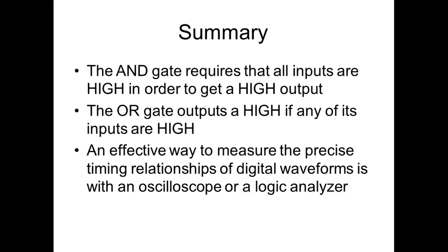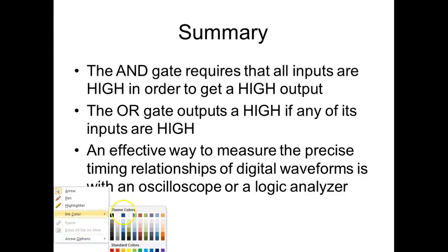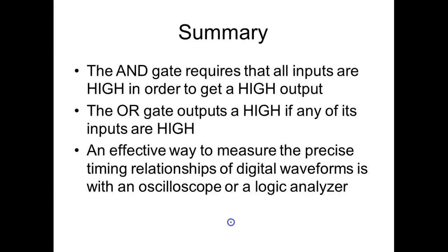for a lot of people, they'll look at an AND gate and they'll say one input is pulsing and they'll see the other input is pulsing. And in their head, they think the output should pulse. But if one of my inputs on the AND gate was pulsing like this, and the other one was pulsing like this, the output will be a solid low.